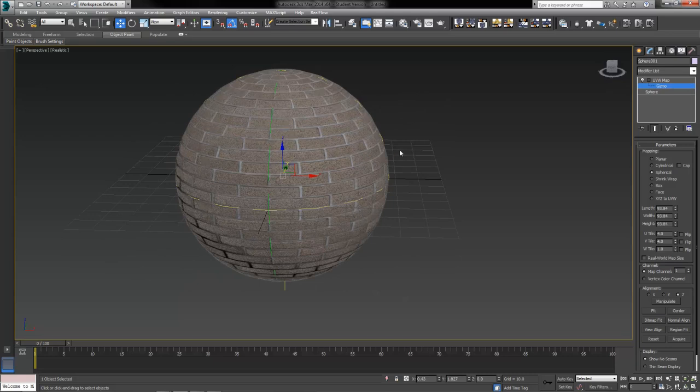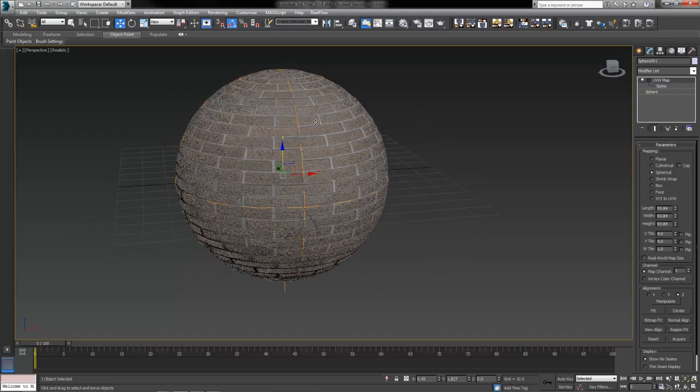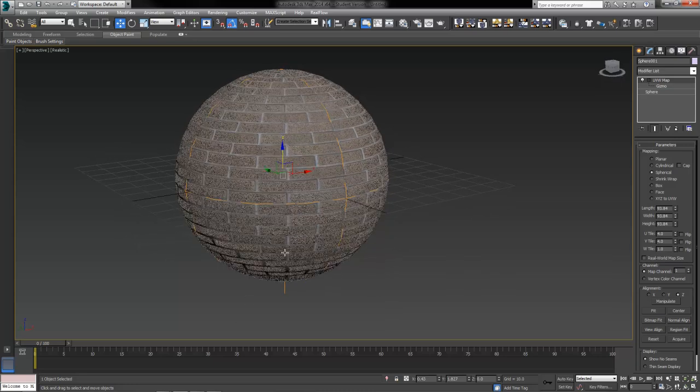Alright, so I hope that gives you a better idea on how these coordinate systems are going to be useful and or work for you here, at least at the very basic, when you start your 3D modeling and texturing. Once you've made these nice textures, you just have to get them to fit your model as best you can, and this is the simplest way of doing it. Again, later on, more complex ways of doing this will be to add multiple UVW map modifiers and or use something a little bit more advanced like the UVW Unwrap editor, which we will get to.